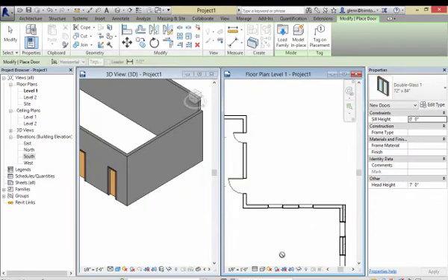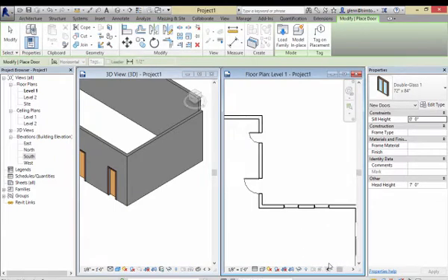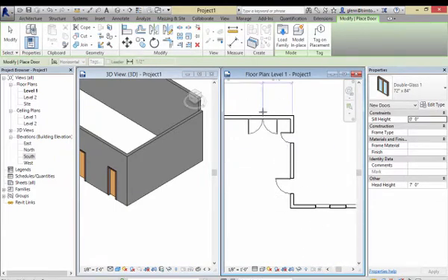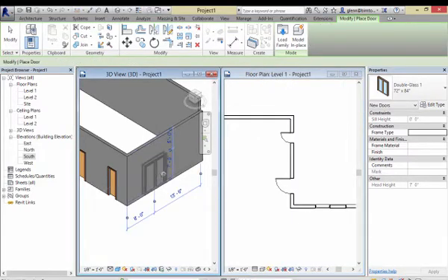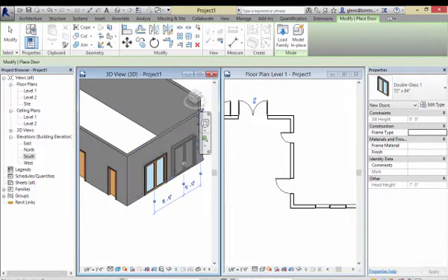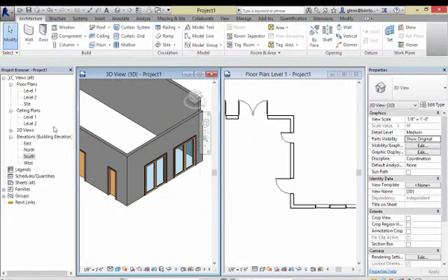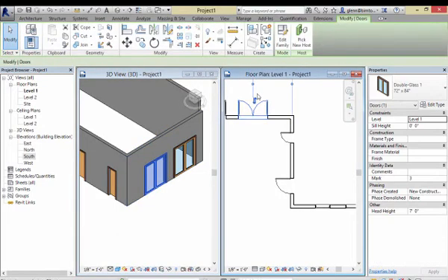I got my double door. I'll open it in here. Let's drop one of these in. So I'll put it in the back wall here. Again, I can put it in 3D also. Come over to this window. We'll put two in there. Okay, got the glass. It's looking good. Oops, mine shouldn't open out. They want to open in, whatever it is. You can flip that all around.